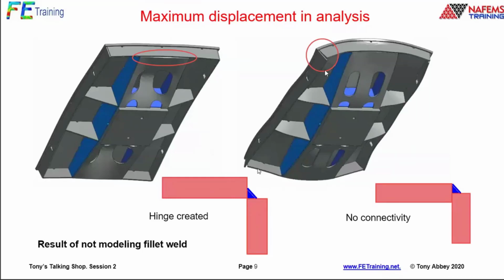This one was an even higher mode shape, and it just happened to catch that edge passes over that edge, and it was a busier, higher mode shape like this that showed it. In that particular case, what was happening was the fillet weld was at some intermediate point, so no node got connected between there. So that mesh and that mesh didn't join up, so we're getting that kind of motion in there.